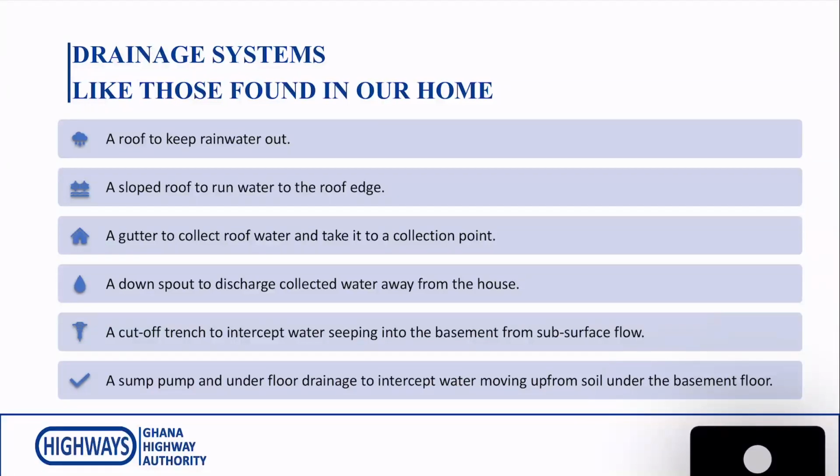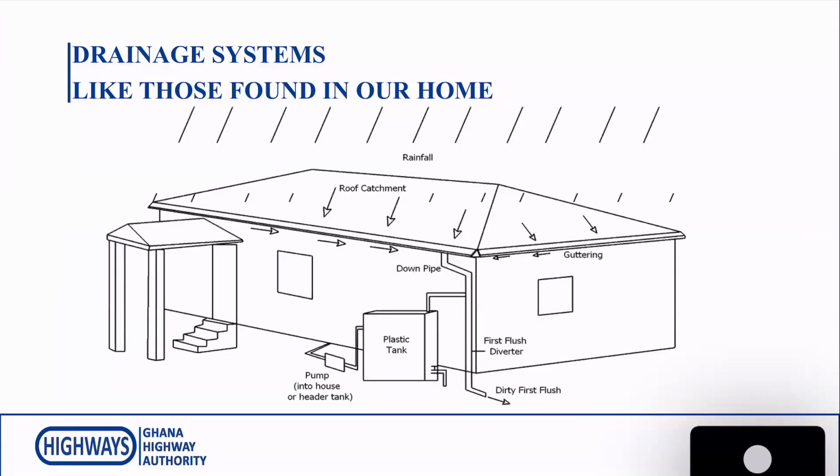Sometimes you need a cut-off trench to intercept water seeping into the basement from subsurface flow, after you have determined that from maybe your geotechnical investigations. You also need a sump pump and underfloor drainage to intercept water moving up from the soil under the basement floor.